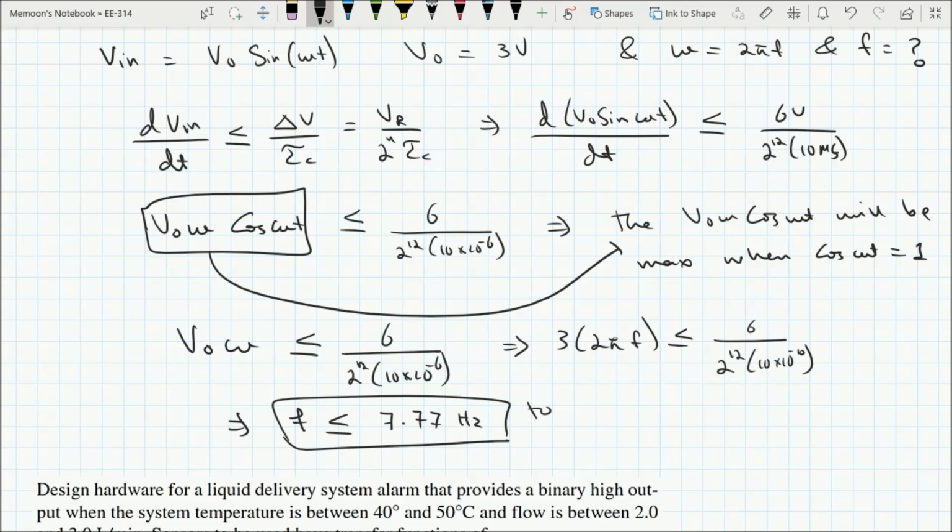So it may result in an effective 11 bit or 10 bit or 9 bit resolution of ADC. We are not right now talking about the sampling frequency or the Nyquist frequency. We are just talking about utilizing the full range or full resolution of our ADC.